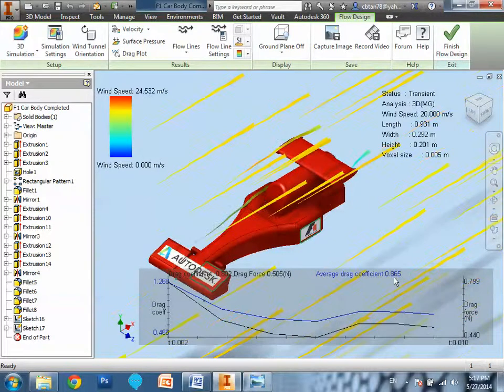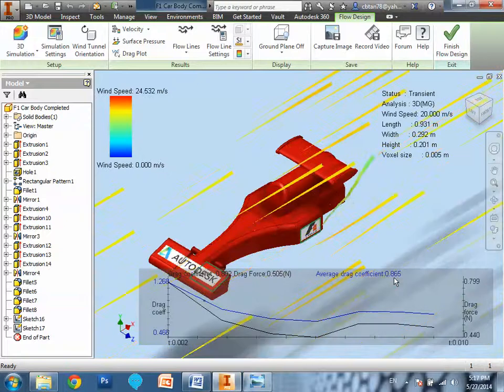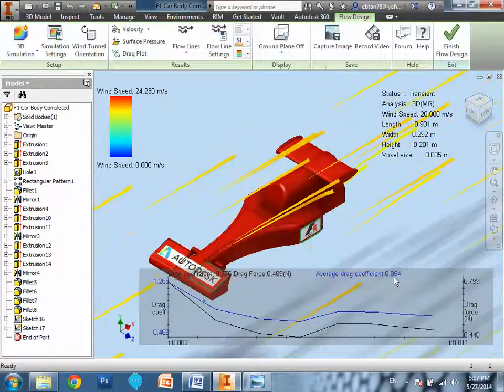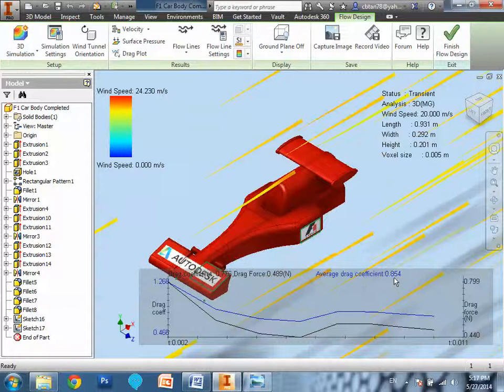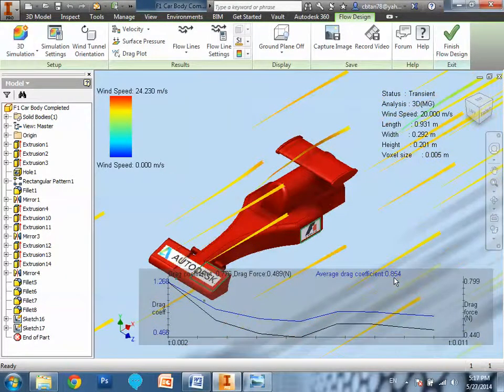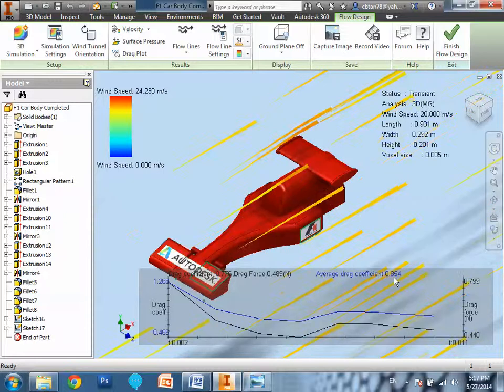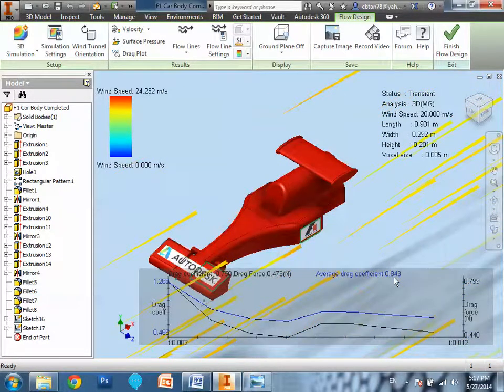Alright. So what the software is actually doing is trying to find the best drag coefficient. It's calculating, simulating. Okay? So when will you stop? Simple. When the two lines meet, that's the ideal case. But we realize that this one, after waiting for 30 minutes, still hasn't converged.